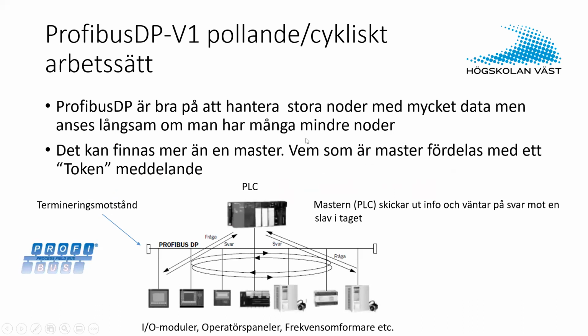Profibus is half duplex, and it's very kind of slow. It has a controller master here that asks each node one at a time in a cyclic manner. So that means it has a large cycle, and it has some kind of time slots, so that when it asks a node for data, the node responds. And yeah, so it's not super fast, probably.